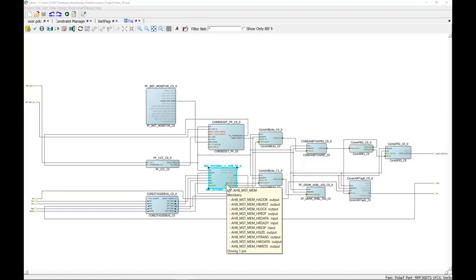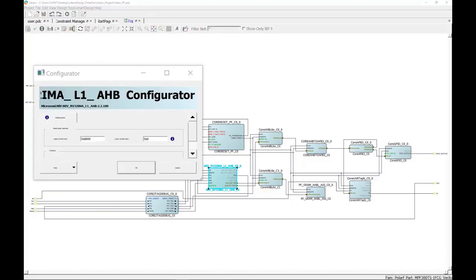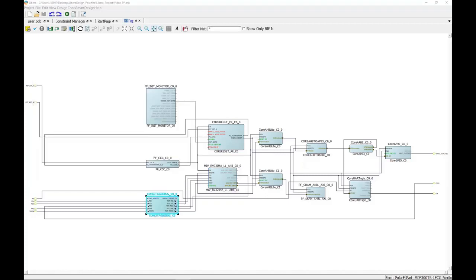This component is the Mi-V soft processor core. The reset vector address is set to 0x8000. This is the address from which the processor will start executing after reset. Core JTAG debug facilitates the connection of RISC-V JTAG debug ports to the JTAG header or GPIO pins. This core facilitates the debugging of the Mi-V core.